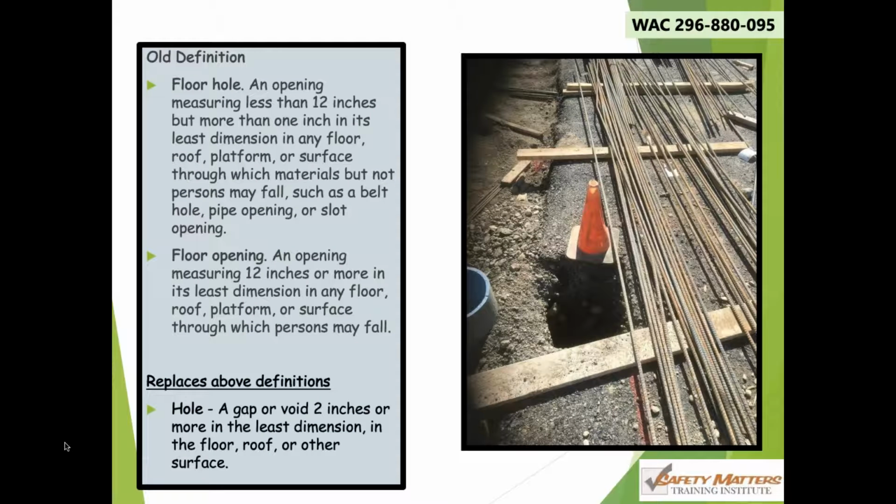What else have they changed? This was a big controversy. They changed the dimensions of a hole and they changed the definition of it. This is one of the weirdest things I still do, when I train OSHA classes versus LNI classes for fall protection. Because OSHA always determined that a floor hole was 2 inches in its least dimension, and yet LNI decided to be really aggressive and say, no, a floor hole was an opening measuring less than 12, but more than 1 inch in its least dimension.